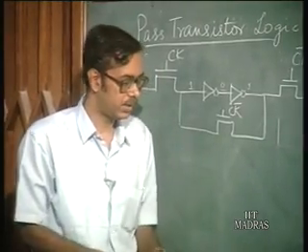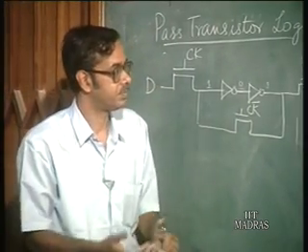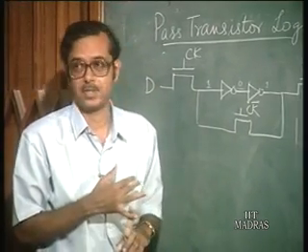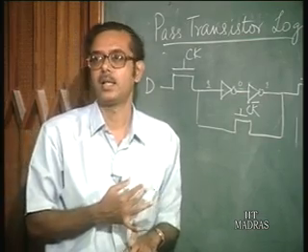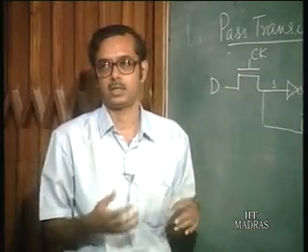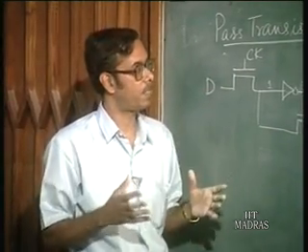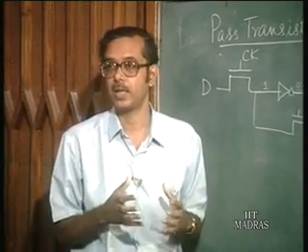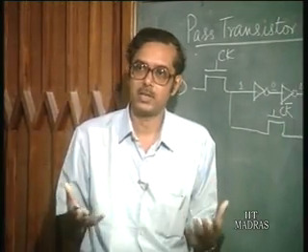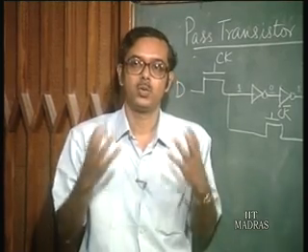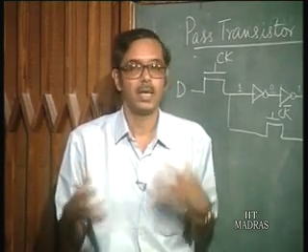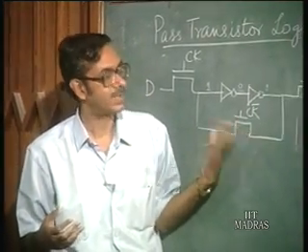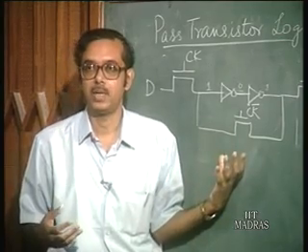That is why it is so popular, because on one hand you save space or area using pass transistor logic, and the power dissipation is also very much reduced, number one because you are saving on a lot of circuitry, and also because pass transistors by themselves do not consume any power.